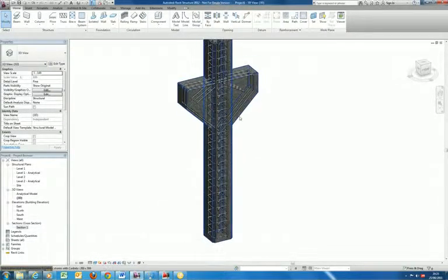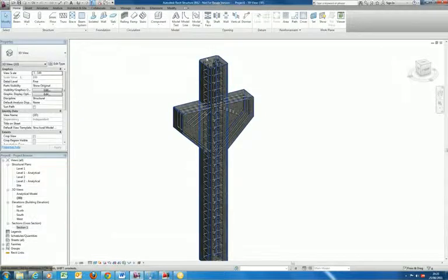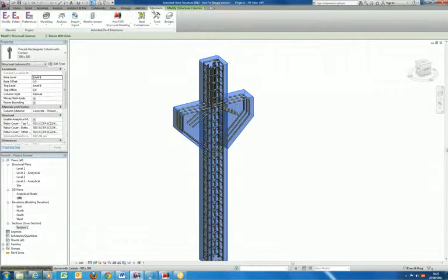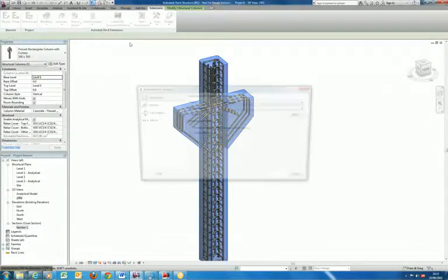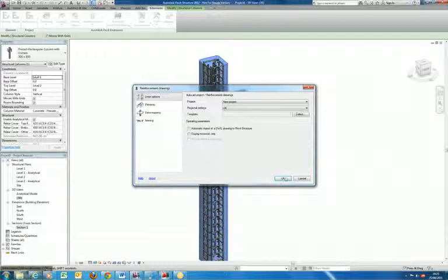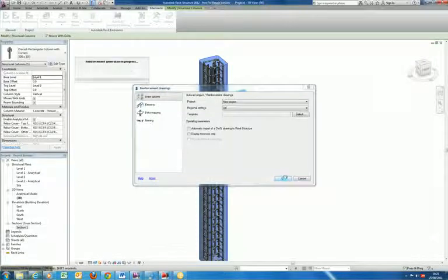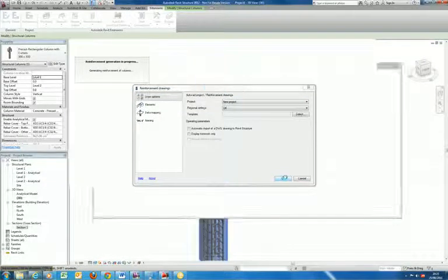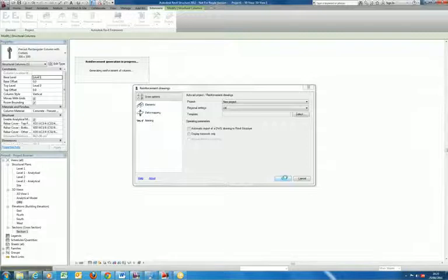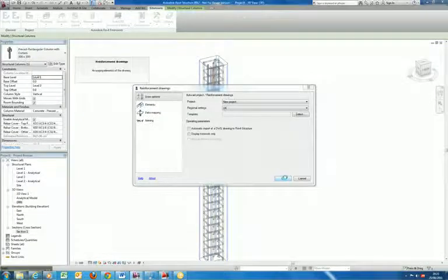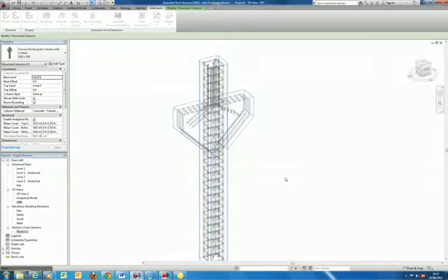So I'm going to select the column up, use my extension, AutoCAD Structural Detailing and reinforcement drawings. I'm going to give this a second, it might take 30 seconds or so, and it's going to export this out to ASD. I'm set up for the UK, so it's going to export out to a standard BS 8666 2005 standard bar scheduling within the UK, but you do have different standards that you can actually physically set up directly in ASD.